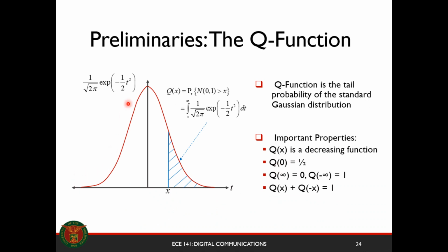So we assume the noise to be normally distributed, right? That's a valid assumption, since we're talking about a large number of electrons, and if you add all that randomly distributed value of your random electron fluctuation, by the central limit theorem it adds up to become a normal distribution.